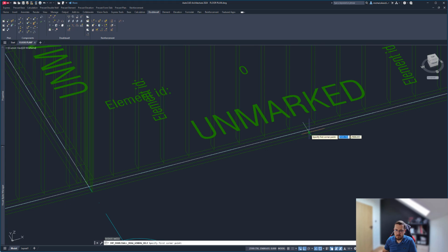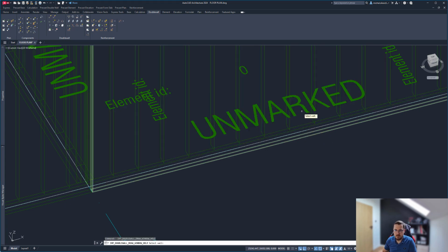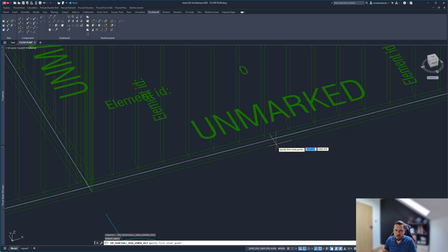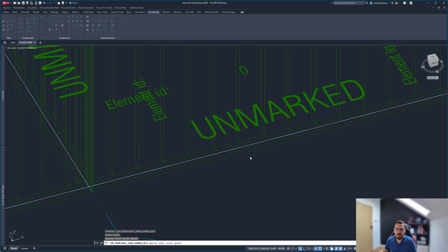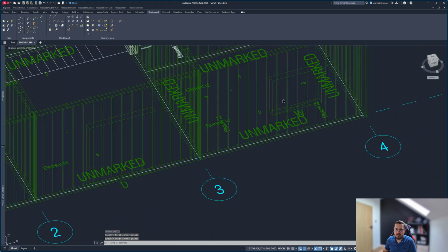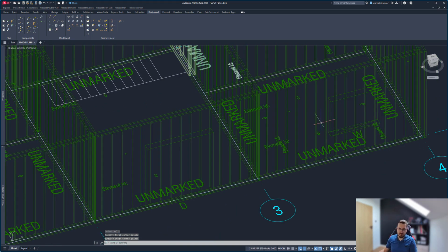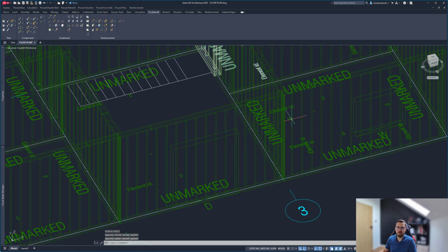Same thing if we go for the window openings. Select this wall. Oops, I didn't select the wall. Okay, first corner here, like that. Let's go 150 distance from floor and 900, which will be perfect. And let's maybe add another end stop as well. Okay, and this is our opening. That should easily cut the meshes later when we do that.